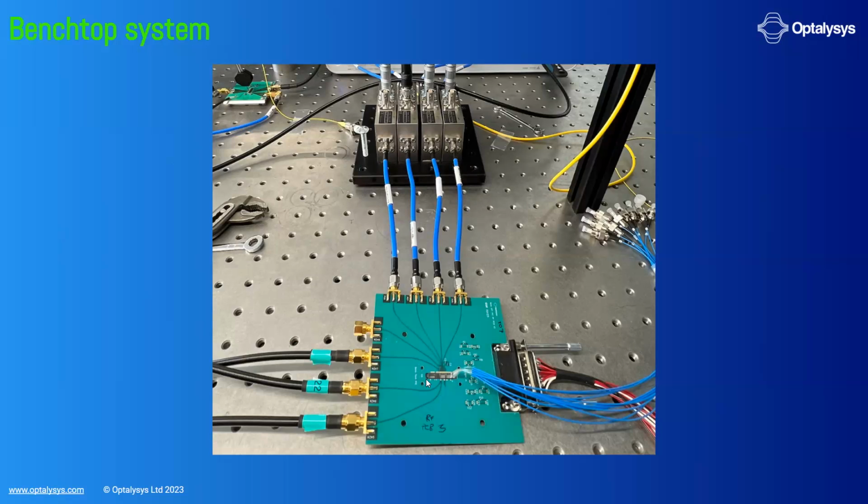It's obviously not the entire thing, that would be quite large, but on this chip, I can assure you there is one of those free space environments that we are currently testing, validating, and hopefully should be hooking up to an FPGA so we can drive very high speed RF signals to the chip, have that control modulators, and we can start working with very high speed transforms, albeit through only one of these free space environments.